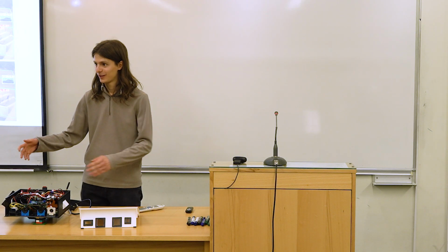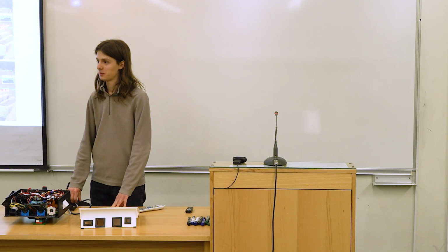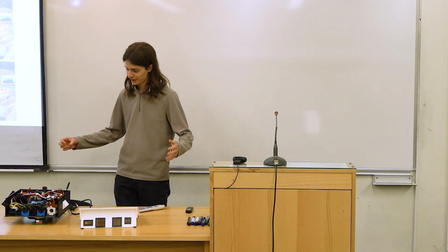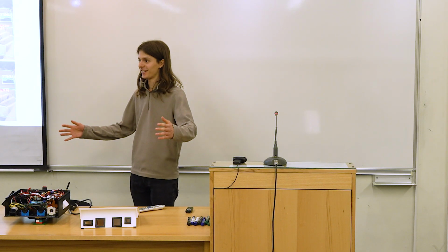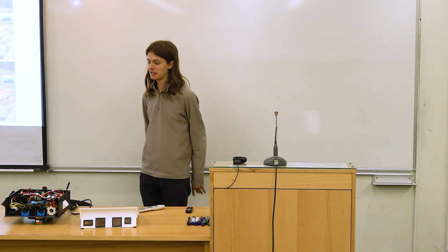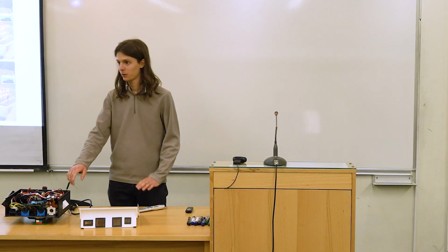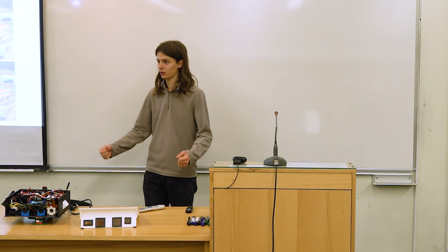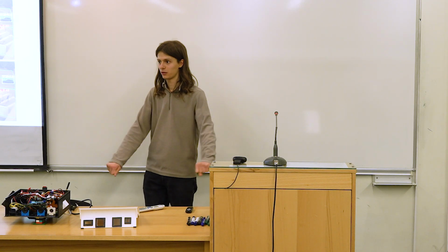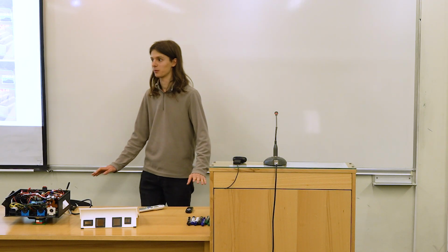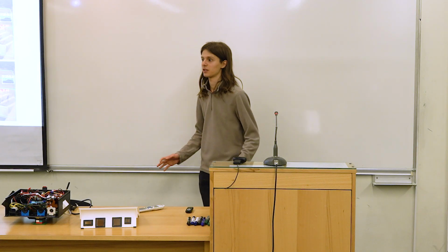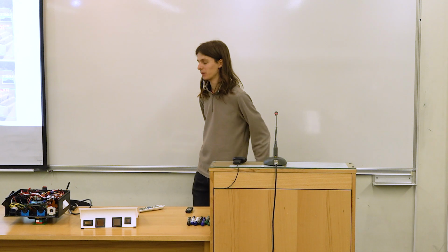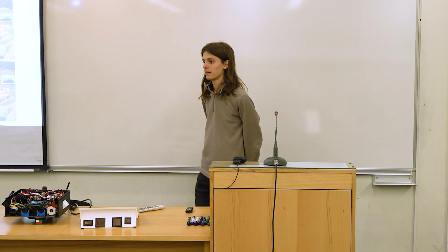Quick question, why ZigBee? It is a communication module that was available. It has a satisfiable range and power, and it can easily connect because it's basically a wireless serial protocol. You just have these two devices, put them into USBs on each end, and it is ready for communication. You don't need any additional configuration, very minimal configuration. Got it. And it's going to work outdoors, right? Yes.